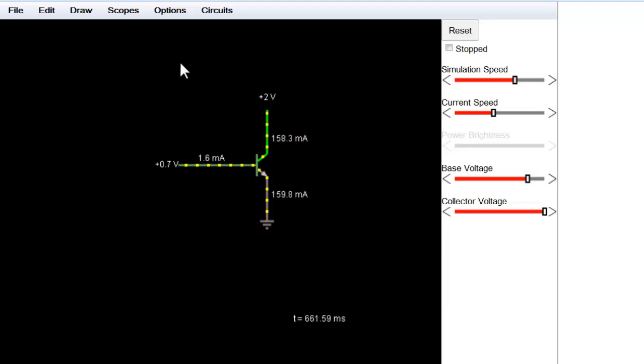So this can be operated as an electronic switch, where this terminal can be given to a microcontroller, where we can control the switching on and off. That means giving a logic high, that is close to this 0.7 volt, to turn on this transistor, and the other one being close to 0, which means this will be off.